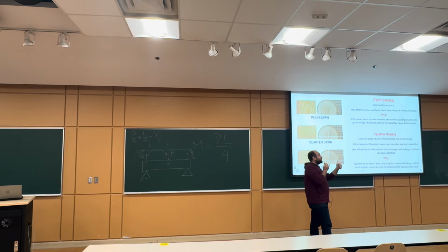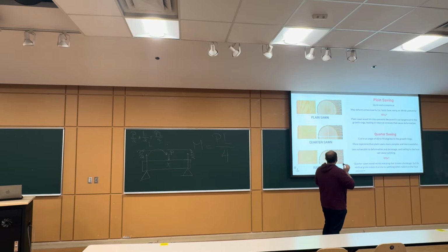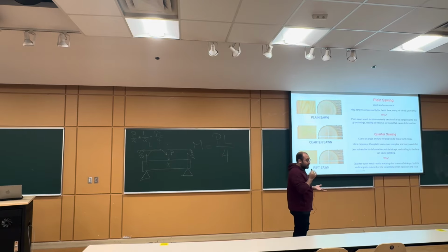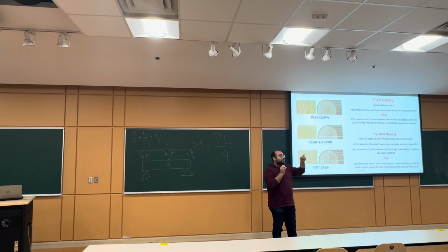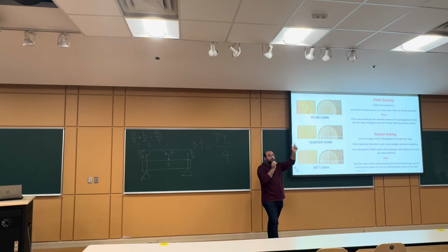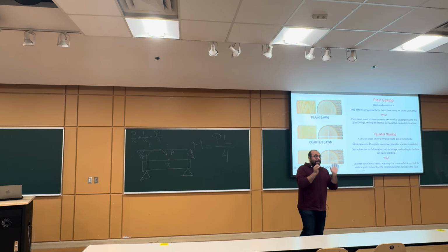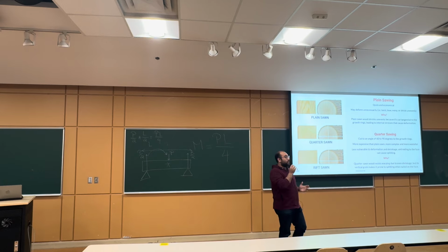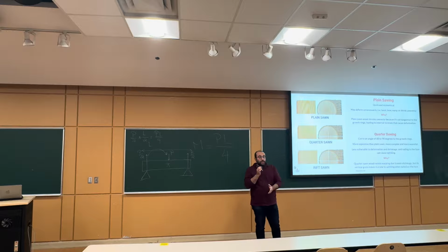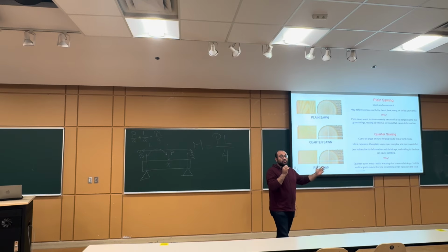Got a question? Yeah. So, the problem here is that it might deform unnecessarily. Why? Because we are cutting in the tangential direction, which means that we have different properties of the material on the tips than what we have at the center. So if the tips, for example, gain moisture at a very high rate and the center does not, this means that there will be deformations between those two poles. And this will cause warping, might cause other deformations, other defects and crack propagations, a lot of problems.